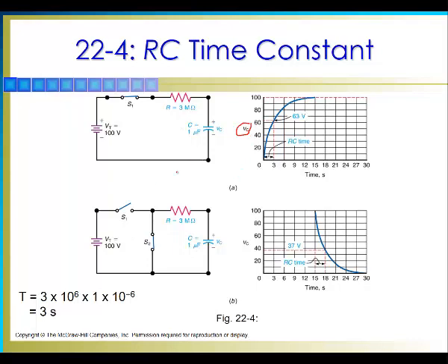Similarly, once the capacitor is charged, we can open the switch right here, and we can put another wire here to short this to make the circuit just be this loop right here. This source now plays no role because it's open. It has been disconnected from the circuit. So this is the circuit now, and the capacitor is fully charged at 100 volts at this point.